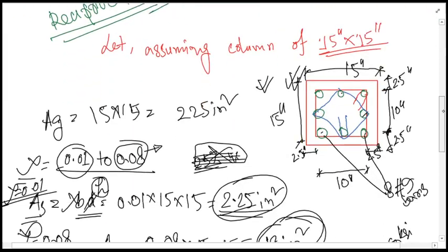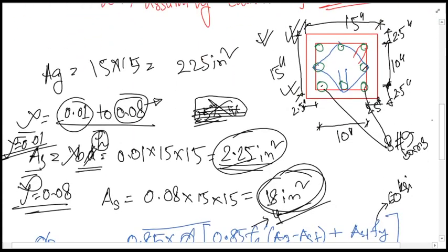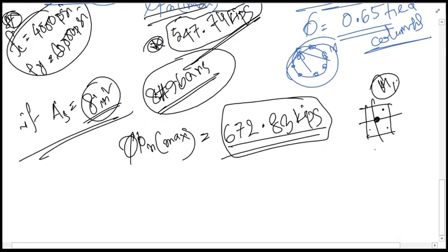You can provide it as I have provided, or you can provide other patterns as well, for example, you might be providing the reinforcement in only 1 layer or 2 layers. This type of reinforcement pattern you can also provide. So based on the pattern, you will have different types of interaction diagrams, and from those interaction diagrams you will have to calculate the reduced capacity of the column according to the reciprocal method, which we'll be going to discuss here now.